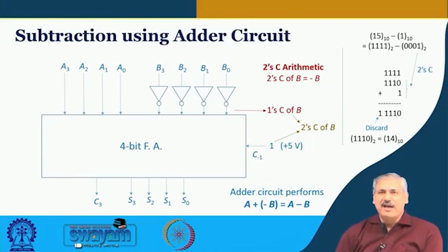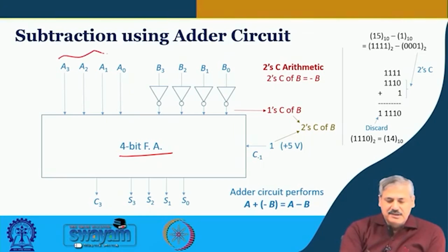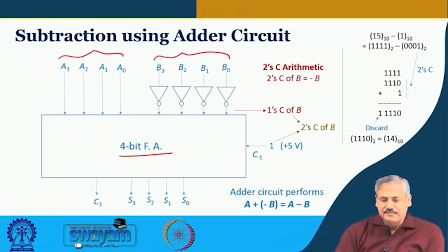So, now what we have got, this is the 4 bit full adder, okay. Within it there are 4 individual 1 bit adders, and we have already seen before how a 1 bit adder is made using basic logic gates, right. So, this 4 bit adder has got these 2 inputs, augend and addend, okay, and this is the sum output and this is the final carry.